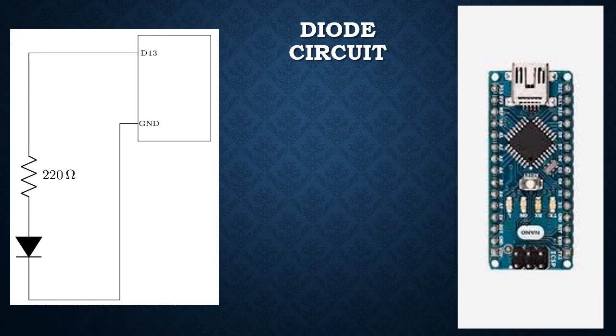And that means that we need to identify the pins that we want to connect wires and then the resistor and the diode to. So it turns out that this ground that's marked in the circuit diagram on the left, we can find a ground pin on the Nano. So I've oriented the picture so that the connector is at the top, and this is how it should appear on your breadboard. This will make it a little easier to do the connection. The ground pin on the Nano is marked GND. There are actually 2 ground pins on your Nano, and you can use either one.